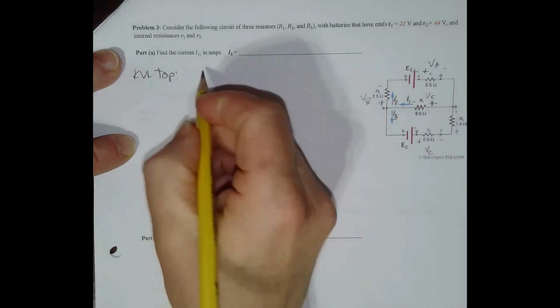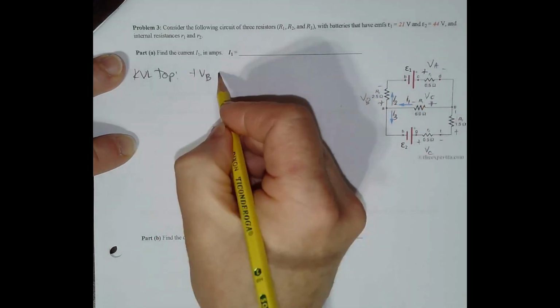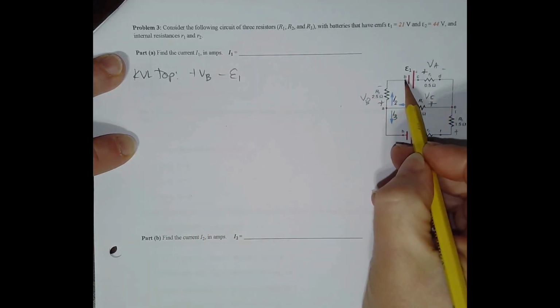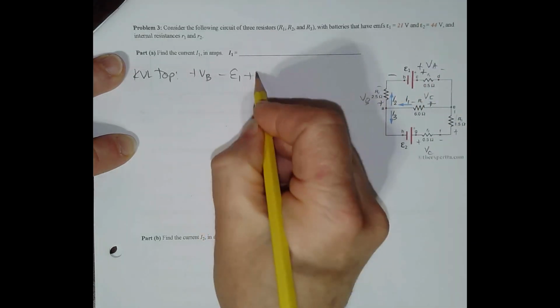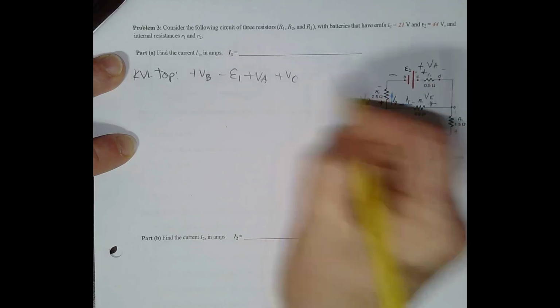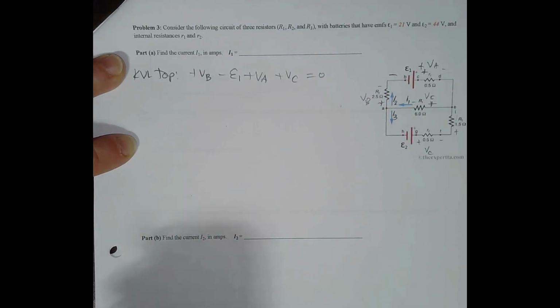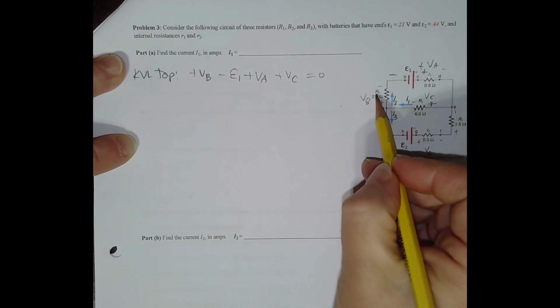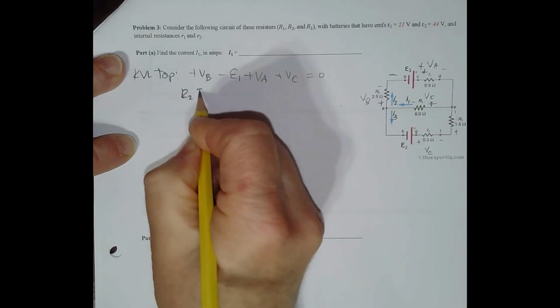So we'll have plus VB minus E1, because we're coming in the small side, right? And then plus VA, coming around, plus VC, back where we started, equals 0. So now writing these in terms of Ohm's law, VB is R2 times I2, right? So let's just write R2 I2